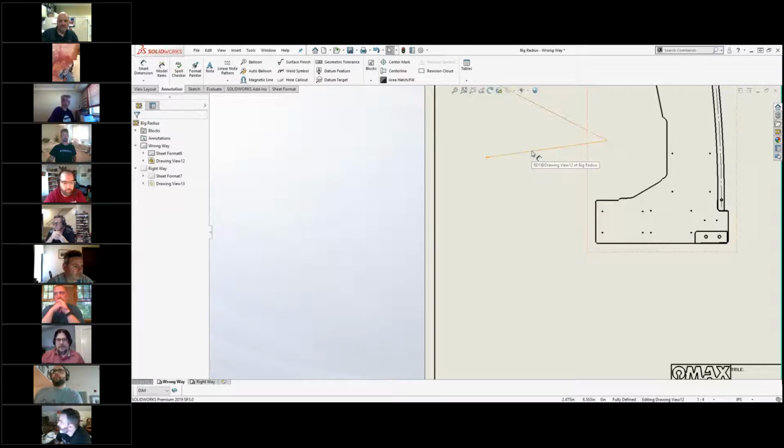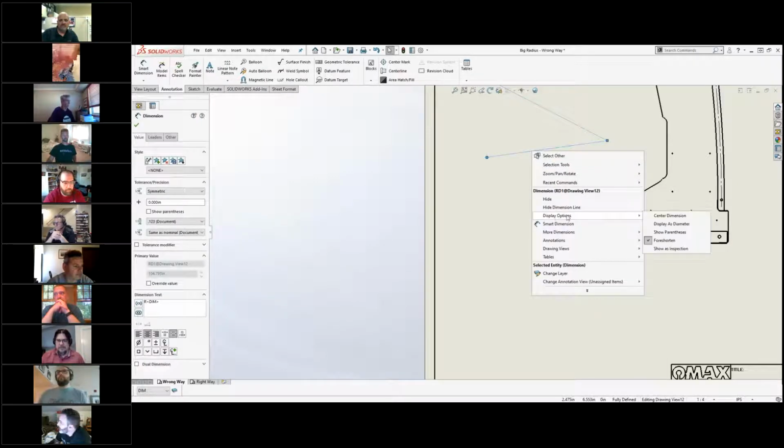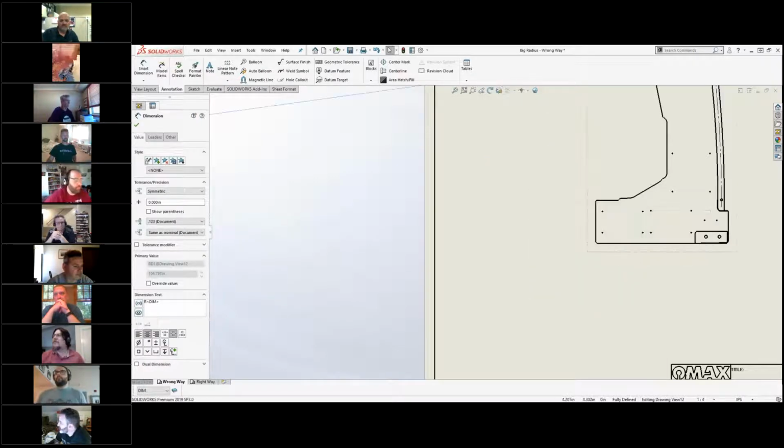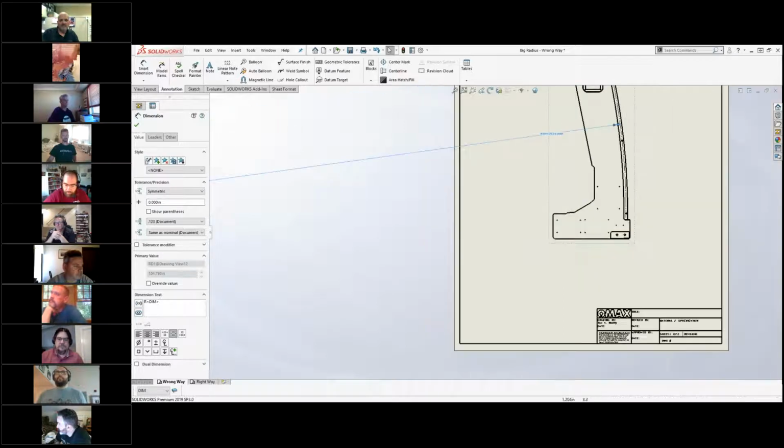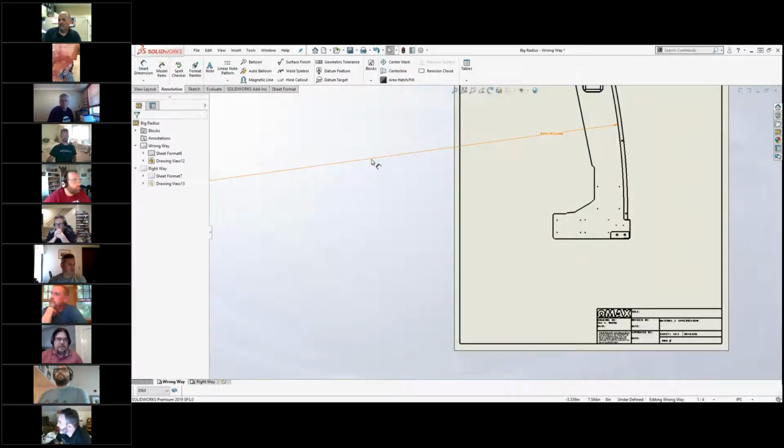Let me go ahead and... Hey, Eric, before you unforeshorten that, try using the shift key with it foreshortened, just to see if it will dimension. Try that, okay. Because when you do radii, you hit the shift, or diameter, it goes inside or outside. Just try it, see if it works. Okay. So foreshorten it. Yep.